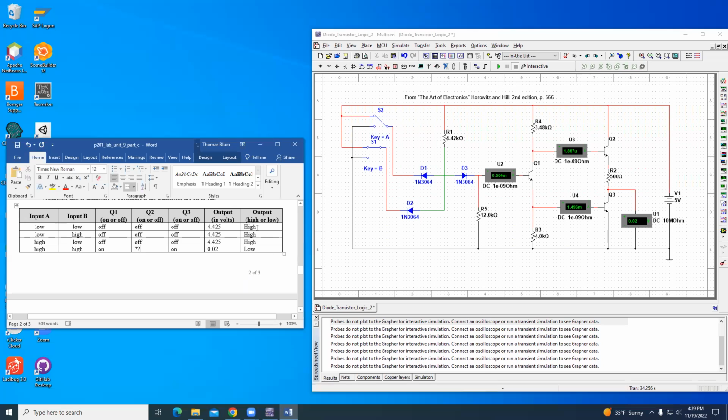Let's think about the opposite of this output: low, low, low, high. We could identify that very quickly as an AND gate, only high when the two inputs are high do we get high. This is the opposite of it, making this a NAND.